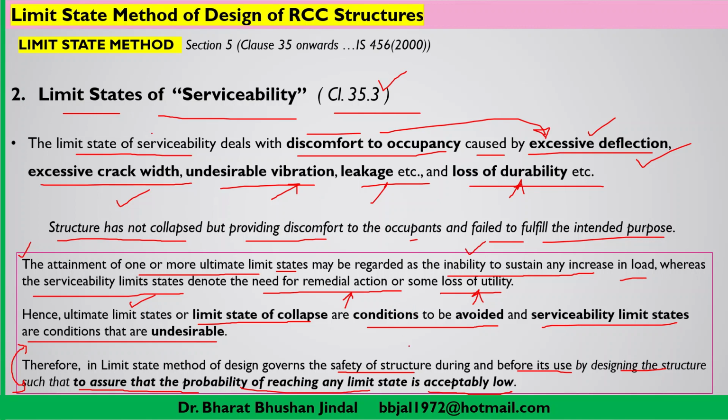So we have to design the structure accordingly. We will be choosing the section, selecting the material, as well as applying various checks. Those checks may be related to strength, deflection, crack width, leakage, durability, etc. All these things we have to take care of while designing any RCC structure with the limit state method.